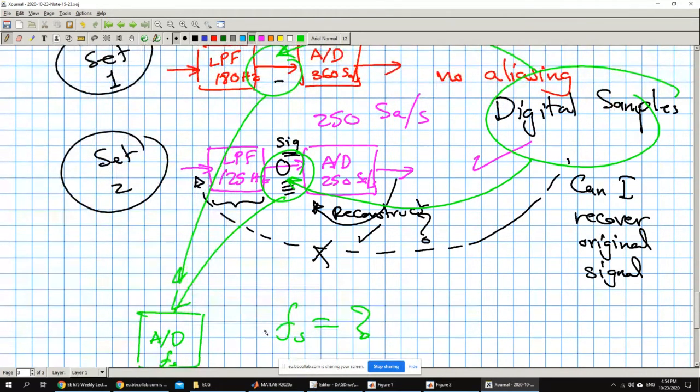First of all, let's consider something else. If I wanted to resample both to be 1000 samples per second, for example, basically, you already have samples at 360 and 250. It's easier to process only one signal rather than process both. So if I consider that I have samples at 360 and resample the 250 to become 360, then I basically need to resample only one signal. I don't need to resample both. And you should minimize the processing effort. There is no point in trying to resample both while you can resample only one.